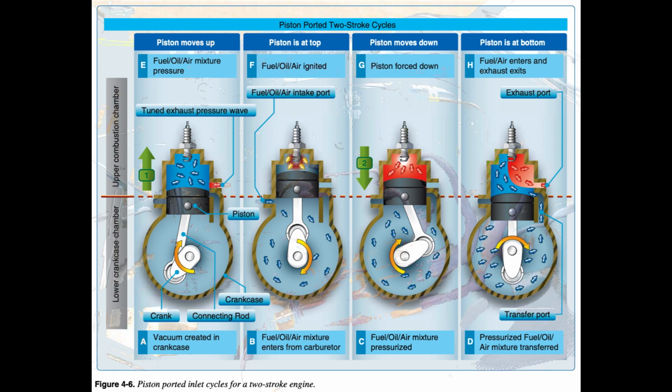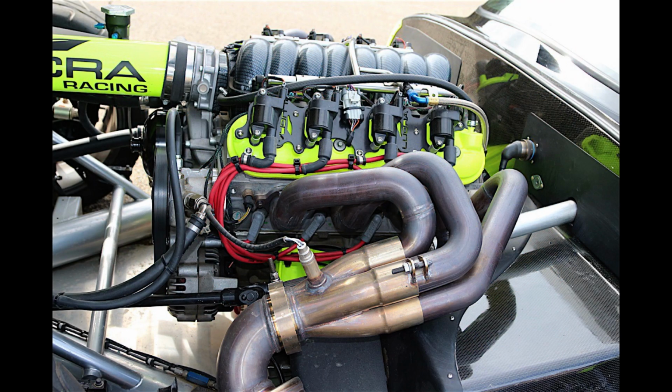Four-stroke engine exhaust systems. Four-stroke engines are not as sensitive as two-stroke engines because they have exhaust valves and, therefore, do not need the precision pulse-tuned exhaust system. However, directing the exhaust out appropriately and reducing the noise are important considerations. Again, using the manufacturer's recommended configurations is required for SLSA and recommended for experimental light sport aircraft, ELSA.